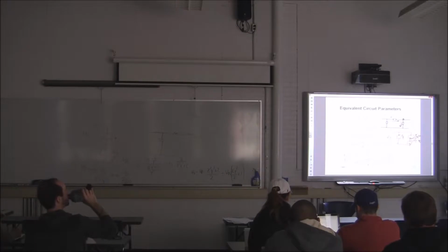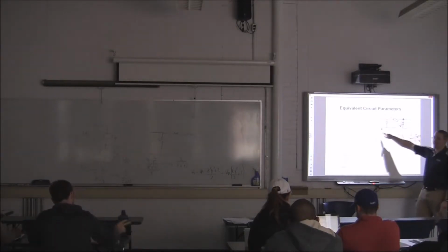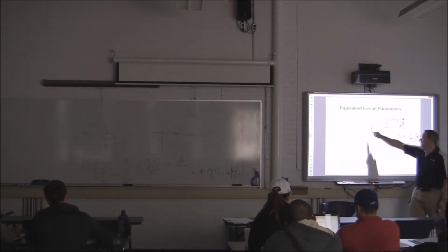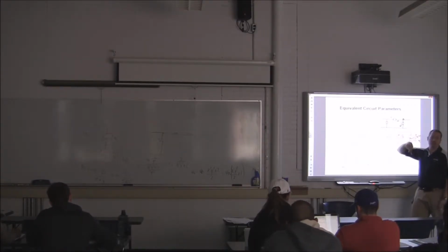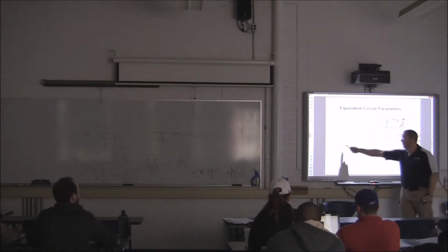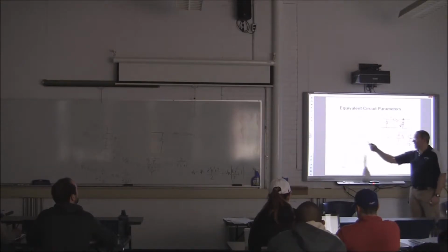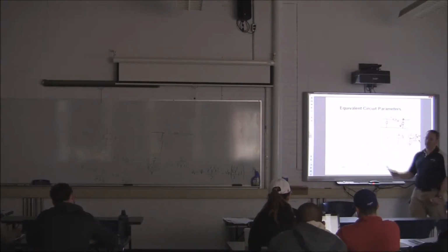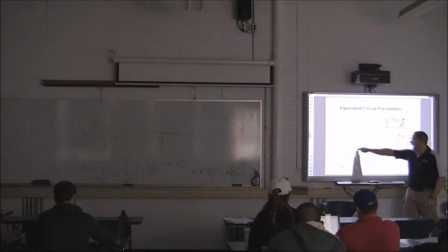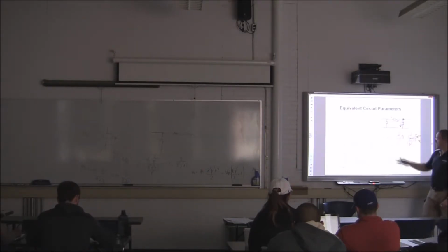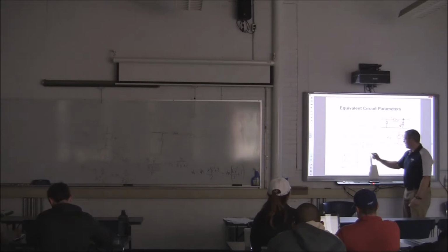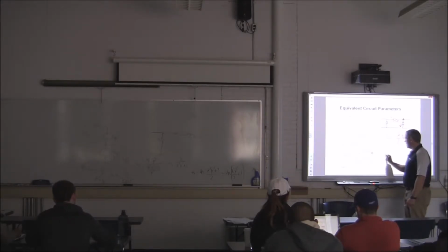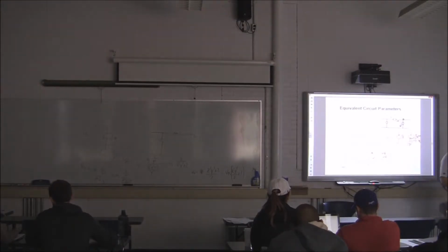So this is set up in standard form, right? This is A times VR plus B times IR, exactly what we need it to be. Same thing over here for IS, and I'm not going to derive this. This is a little more slogging, but you can get there from here. This is A times VR plus B times IR. So this is equal to A. This is my B term, my C term, and my D term.